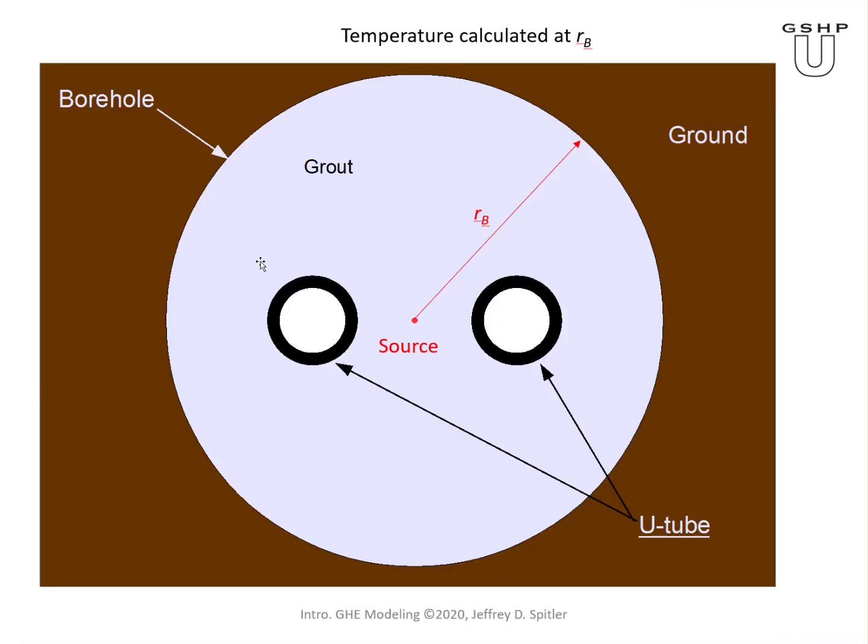And even if they're perfectly straight, it's unlikely the U-tube is going to sit exactly in the center, so symmetric. But we often think of it as, on average, it looks something like this, where the spacing between the two tubes is about equal to the spacing between the tube and the outer wall. There's some empirical evidence for it, but not a lot of hard proof.